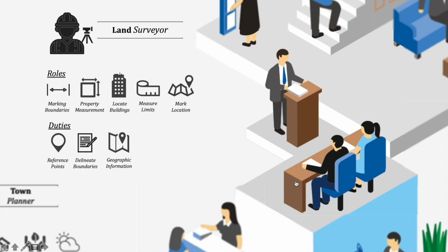Other than that, the responsibility of a land surveyor includes recording the space positioning and angles between 2 points on the ground, and also using agreed upon reference points called benchmarks as a starting point. Additionally, the land surveyor will carefully delineate the boundaries of interest by using both their on-site surveys and records found in land offices to write the legal description of a parcel.